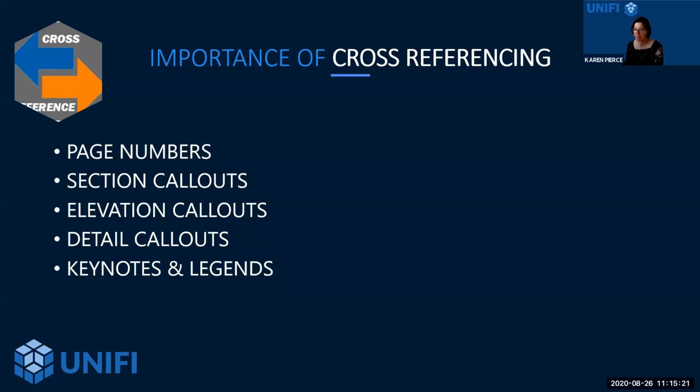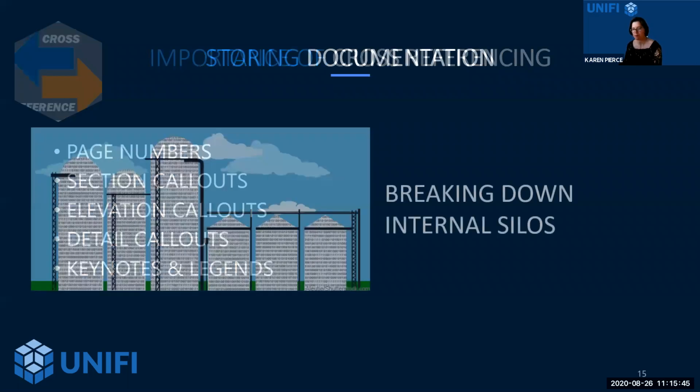I have simply A101 for my first floor plan, but I actually have A001 to designate a demo. And I have A201 to designate the next phase of the project because I have to have multiple phases. So there's all different types of complexities that, with your page numbers actually being properly planned out, you'll be able to very easily cross-reference all the information you're going to need to.